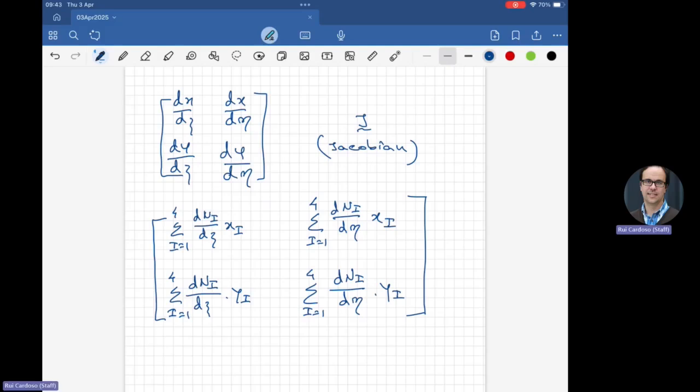Well, it depends on the elements you are using in your mesh. You need to check in your coursework which elements you have. Is it shell elements, plate elements, beam elements? I don't know which elements you have. The number of divisions defines the mesh. You need to figure that out.